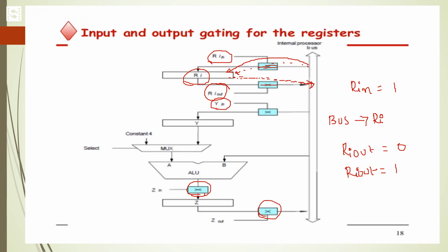All operations and data transfers within the processor take place within time periods defined by the processor clock. The control signals that govern a particular transfer are asserted at the start of clock cycles. The register consists of edge-triggered flip-flops, and the clocking methodology defines the timing of read and write operations.